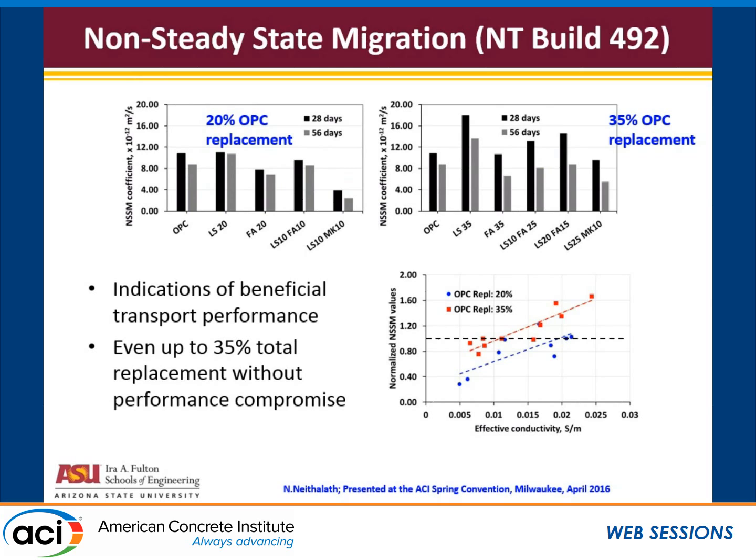60 volts for 6 hours creates a lot of heat. You have Joule heating effects too. This you typically do at 30 volts or lower, which means the heating effects are much more reduced. The ionic transport is much more under equilibrium rather than very highly forced conditions. You have a 20% replacement of cement system here, 35% replacement total.